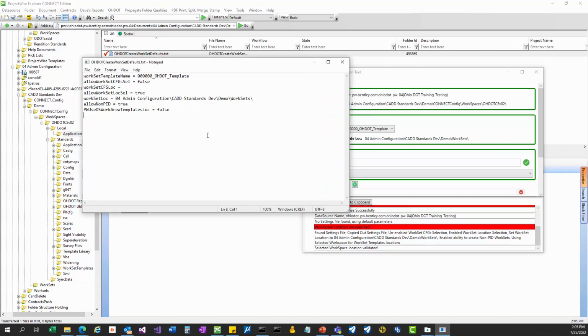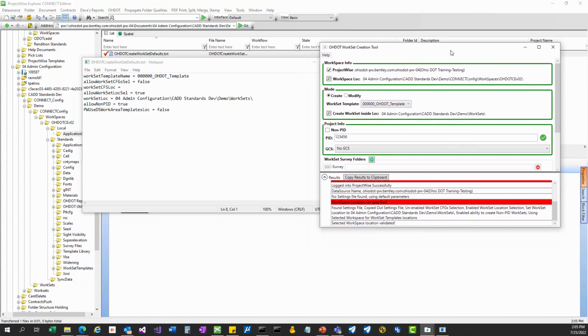Okay. So moving on with the application, the next setting would be the coordinate system. So all of our projects should have a coordinate system. Right now there are 2 options, north and south zone. If you are doing a custom coordinate system, typically the surveyor would set that up, and then we have other documentation on how to do that. But this will give you seed files for the project with the coordinate system already set that you have chosen.